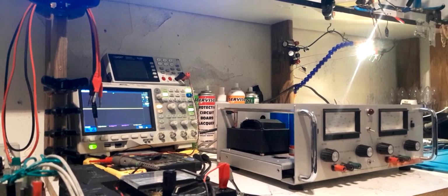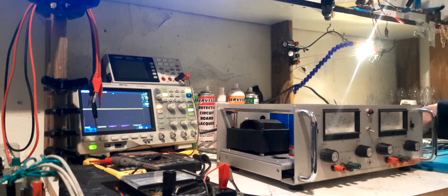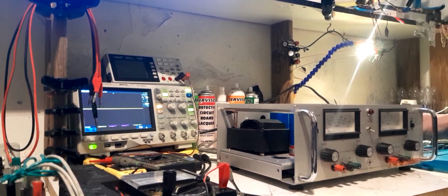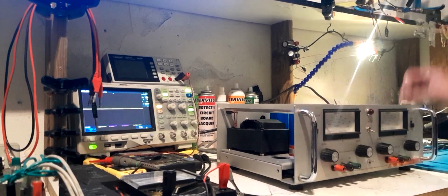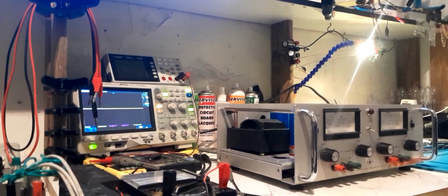You'd put that in parallel with say a 0.01 and a 0.1, to cover a wide range of frequencies in your filter. Nowadays you'll see just the bulk electrolytic cap and a 0.1. Sometimes you'll even just see a 1 microfarad cap, like the little ones I was using on the op-amps, these little multi-layer monolithic chip capacitors. They have excellent frequency characteristics, and just one of those does the business, right?